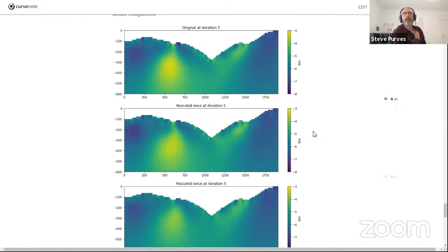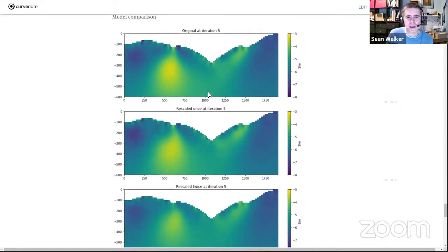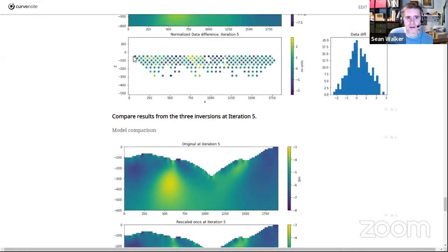Well, yeah, definitely the longer dipoles, in theory, do see deeper. That goes back to what we were talking about: this data point here isn't really the same as this point here, because the currents are flowing all through the near surface. So the currents that are input are also changed. That's why it's generally the normalized voltage that's put in.